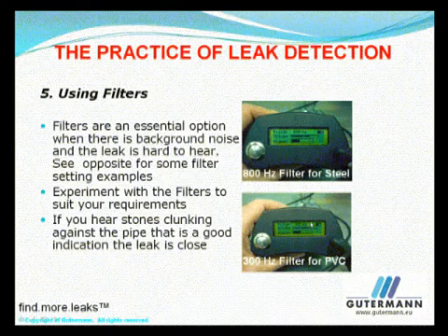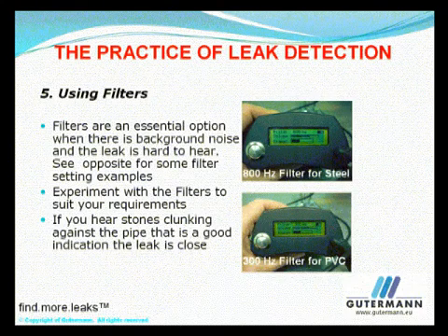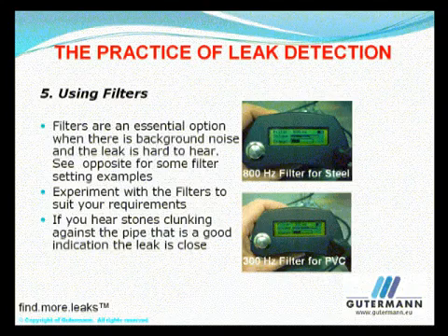Good use of filters is essential in finding quiet leak noise that is muffled with background noise. To prepare your skills for using filters, it's advisable that you familiarize yourself with tuning into the sound of a leak at every opportunity you have.